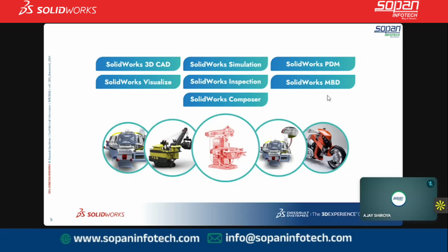SolidWorks MBD helps organizations communicate manufacturing information directly on the 3D model, reducing dependency on traditional 2D drawings. It allows us to define dimensions, tolerances, annotations, and manufacturing information directly through the 3D model.